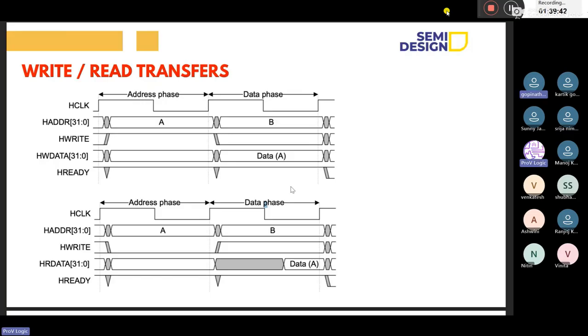So that is the thing, right? In the address phase only, we select whether it is a write or read transfer. So we have two phases to do the transfers in AHB. In the address phase, we finalize our control information, and in the data phase, it only transfers the data based on the write signal, on the size, on the increment, all these things. Is that correct? Yes.